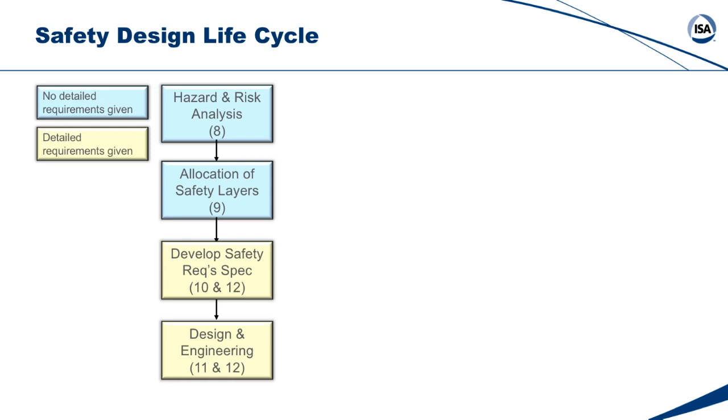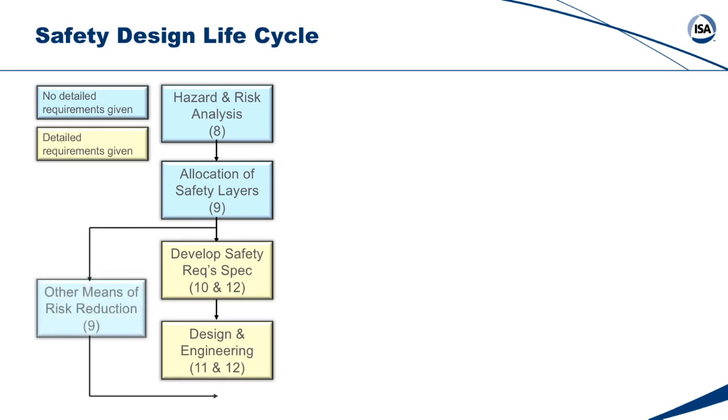Clause 11 is detailed requirements in hardware design, how you respond to faults, fault tolerance issues, interface issues, bypasses, all sorts of things. Clause 12 on software design. And that's about the only thing that falls on the system integrator, is the actual building of the system to the specification that they should have received from other parties.